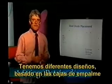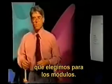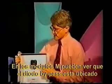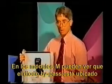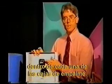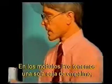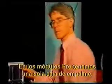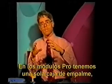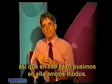We have different designs based on our junction boxes and so on that we've chosen for our modules. In the actual module itself, you can see in the M-series of modules, the bypass diode is located inside each of the junction boxes. In the case of the Pro series of modules, we have one single junction box, so in that case, we put both diodes in the junction box.